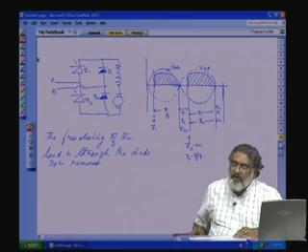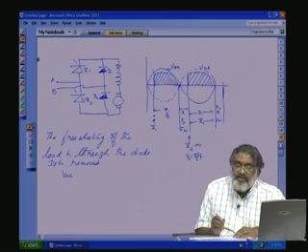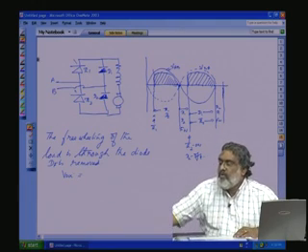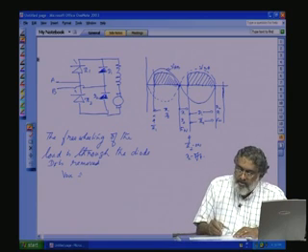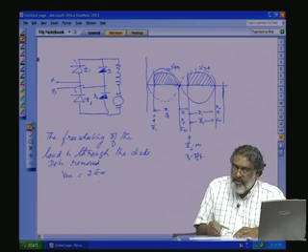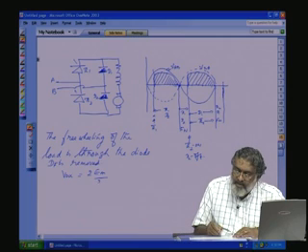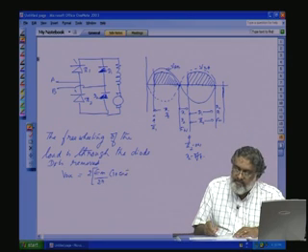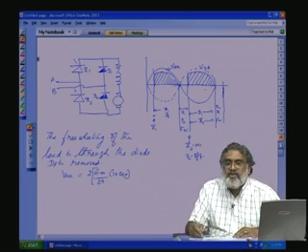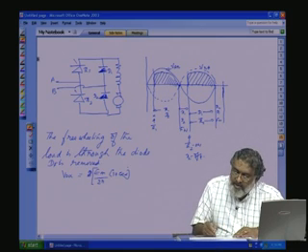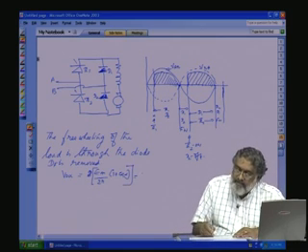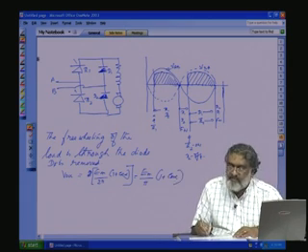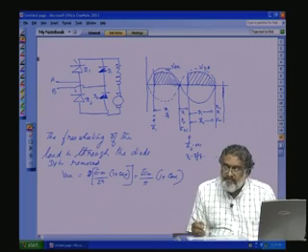Here also the output voltage V0 alpha, that means output V0 DC with respect to firing angle alpha, is equal to how much? Here also, for half wave it is EM by 2 pi into 1 plus cos alpha. Now, the other half also, during the negative portion, we are getting the output ripple. So, it is 2 times EM by 2 pi, that is equal to EM by pi into 1 plus cos alpha. This is the output voltage ripple.